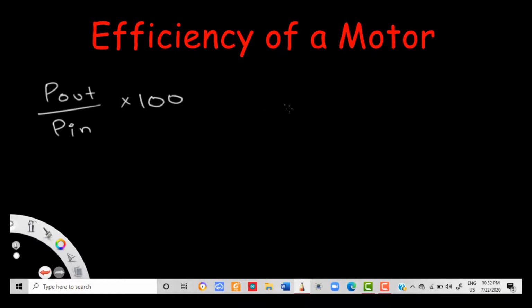Every single motor on earth, single phase motor or any motor, will have a horsepower rating, which is its mechanical capability rating. Okay, so how much it can mechanically run, that is compared to a horse, given the name horsepower. And 1 horsepower equals 746 watts of power. So now we have something that relates the mechanical world to the electric world. We know 1 horsepower, which is mechanical, will equal 746 watts, which is electrical.